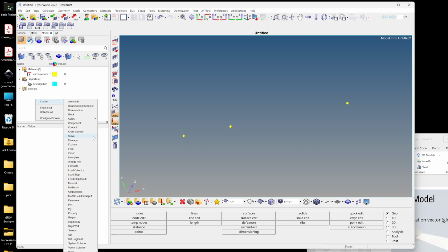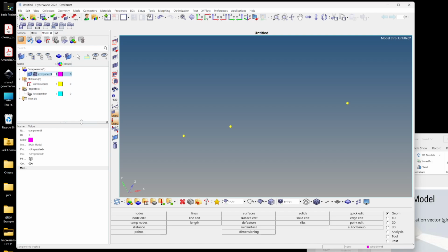Like maybe the forward wing will be on a different component level, the winglets might be on another one, the ailerons on another level, so to speak. So we'll do that, and we'll make a component, right? So we click on component, and we'll give it a name, fuselage, okay? And that's fine, and you can see it's active.